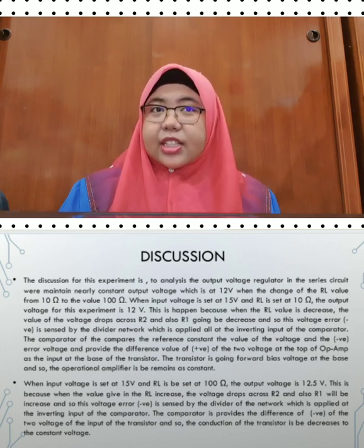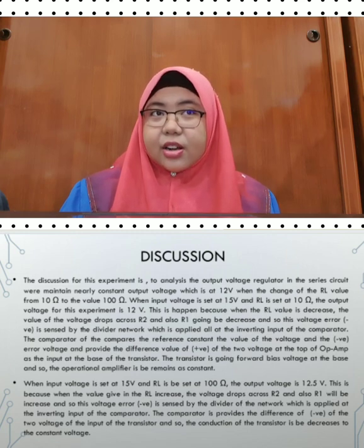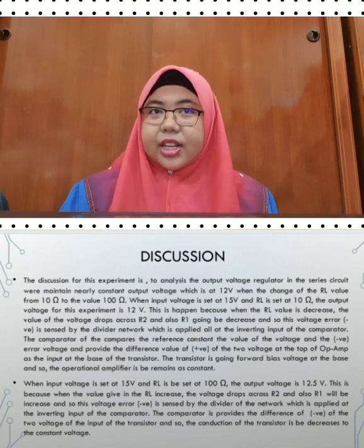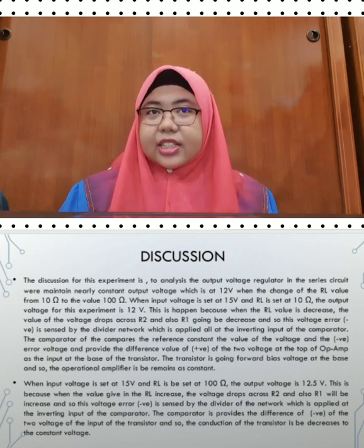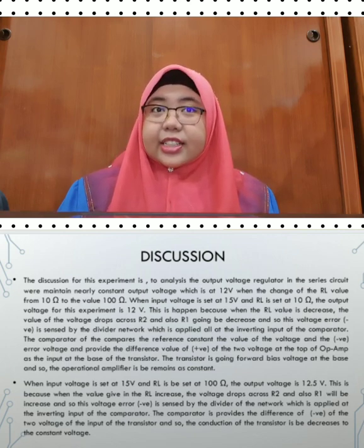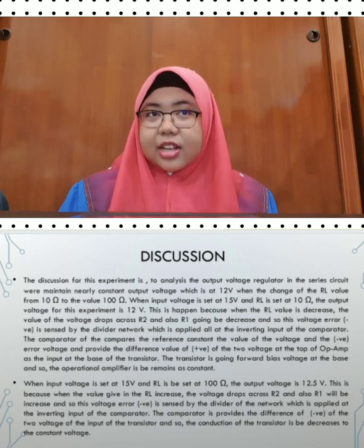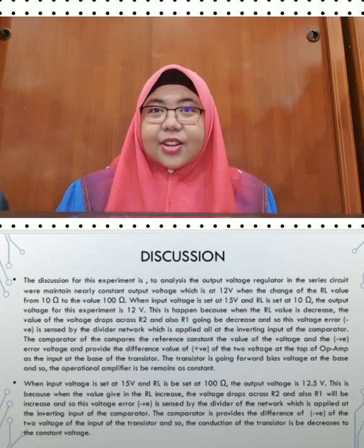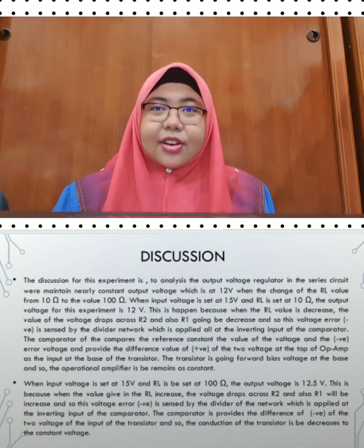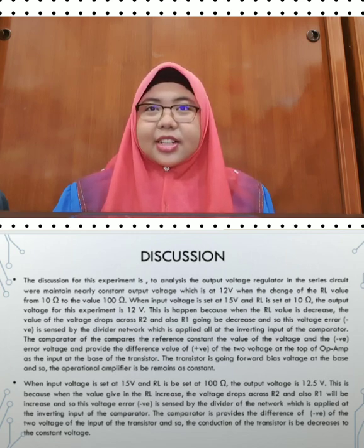The comparator provides the difference of the two voltages at the input of the transistor, and so the conduction of the transistor is decreased, so the output voltage stays constant.